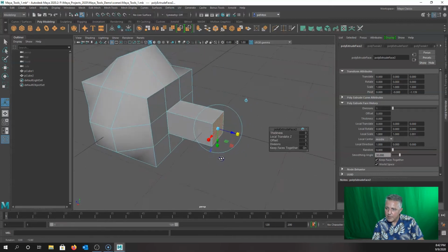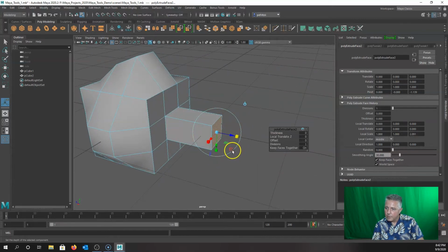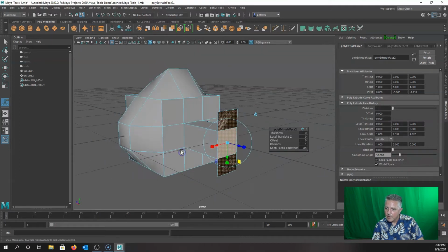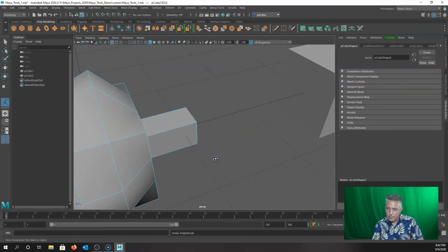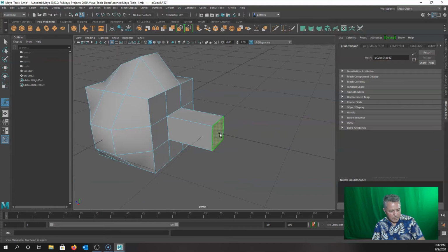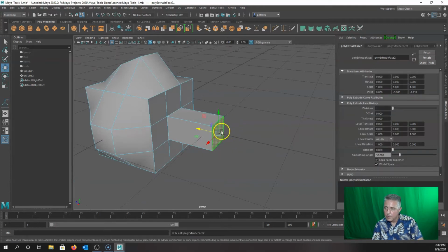Some of the things that can happen if I don't do this correctly is I can mess some things up. I can accidentally select the wrong piece. I'm going to go ahead and Control Z back out of that. Now if I select it again, hit Control E, hit W, bring up that tool, I can extrude it on top of it again.